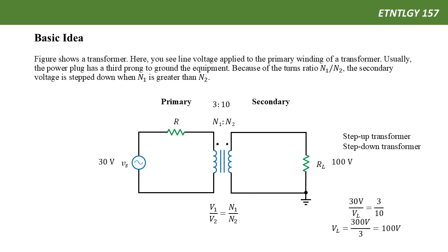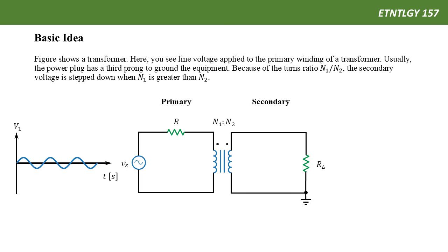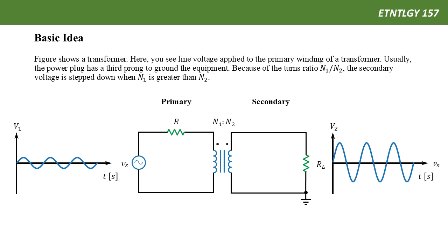The schematic for a transformer is in the center of the circuit, between the primary and the secondary sides. As you can see, a transformer is made of inductors. The symbol shows two inductors, one on the left and the other on the right. Between the two inductor symbols, there are two parallel lines. It represents the magnetic core. The electrical energy, the sine wave, will reach from the primary side to the secondary side wirelessly.